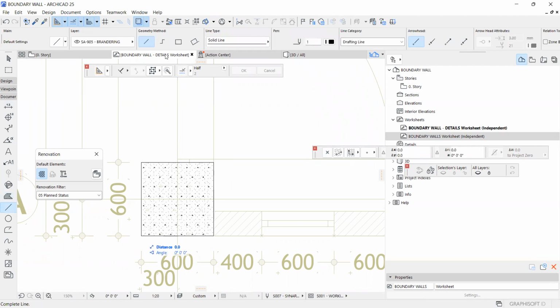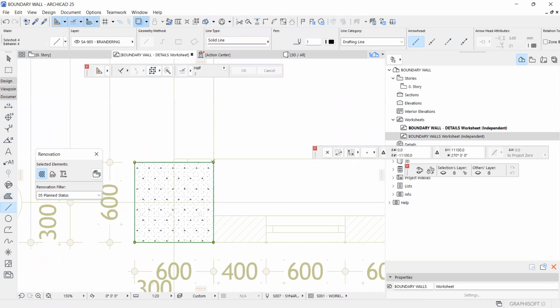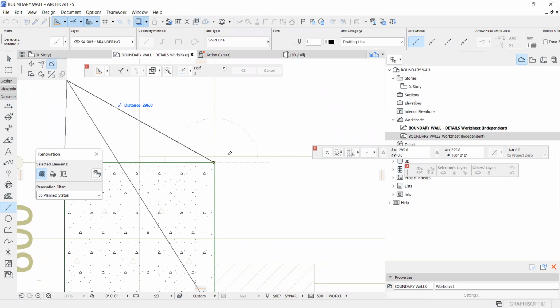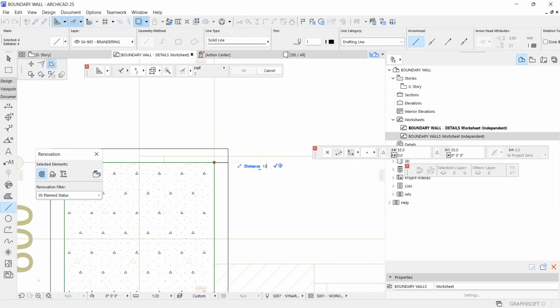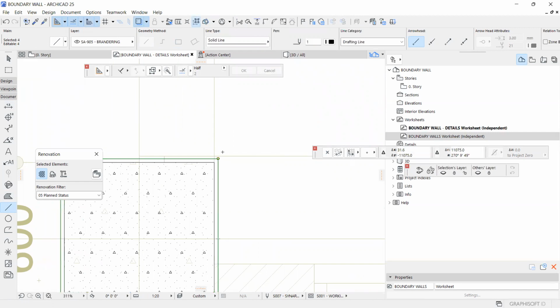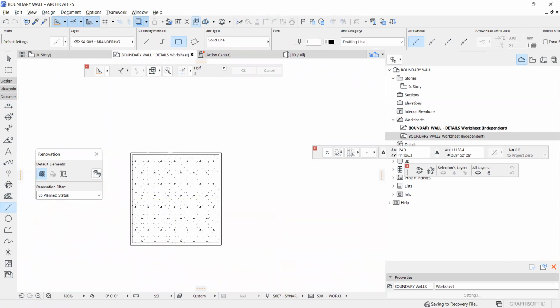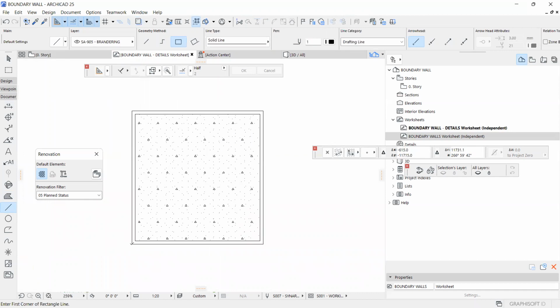Now, normally for columns, normally plaster. And the plaster on average is usually half an inch. So we can work with around 15. So we'll have a 15 millimeter thickness of plaster. And then once you have finished the 15 millimeters of plaster, you'll paint. Paint usually 3 coats.